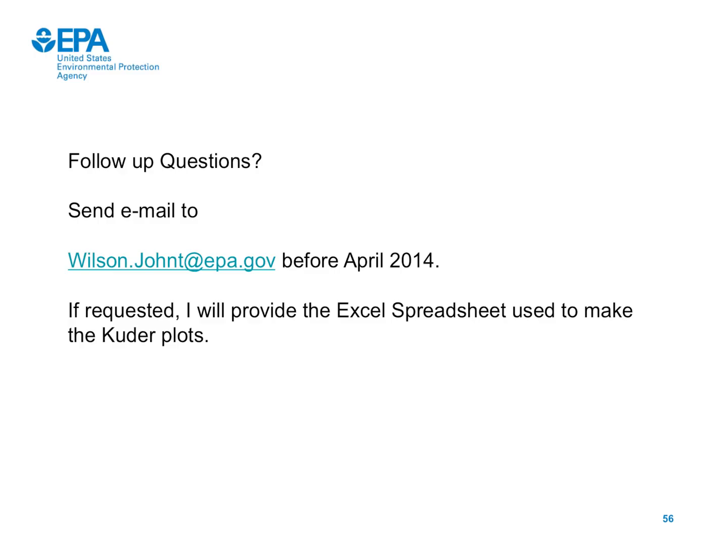Okay, how does absorption on naturally occurring organic material affect the CSIA approach to determine degradation? Absorption mildly fractionates the TCE. And so if you are looking at a plume that is expanding and you're at the leading edge of the plume while it's growing, it could mislead you into thinking it's degrading. Most of the time, because we quit using TCE in this country 30 years ago, you're looking at plumes that have stabilized as far as sorption goes. And so sorption no longer has an effect on the fractionation, and it doesn't matter.